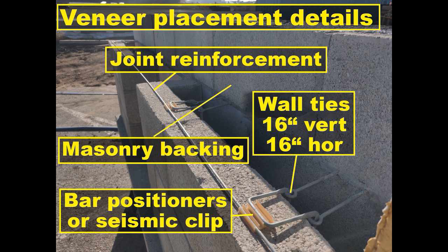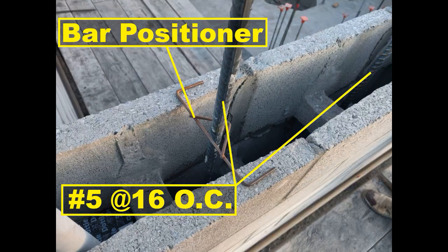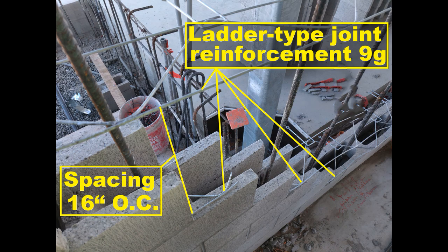Provide adjustable type wall ties that consist of 2 essentially U-shaped elements that are inserted into eyes of horizontal joint reinforcement, hot-dip galvanized. Form the pintle and eye elements so that both can be in the same plane. Bar positioners. Factory fabricate bar positioners, used to prevent displacement of reinforcing bars during the course of construction, from 9-gauge steel wire or equivalent, and hot-dip galvanized. Bar positioners must be suitable for intended use and be corrosion-resistant steel. Bar positioners not fully contained within the width must be hot-dip galvanized.